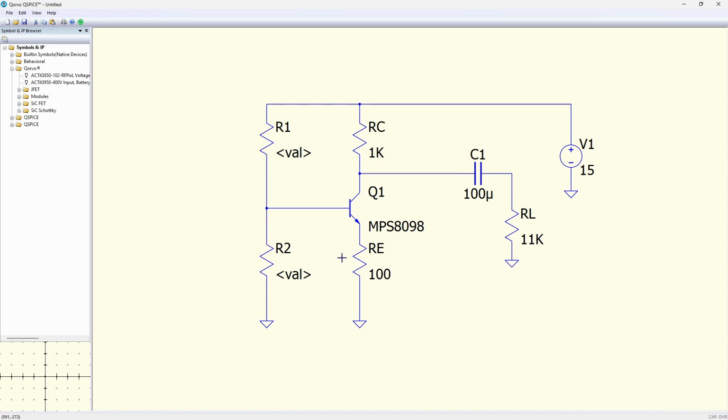But if we have 100 ohms here, now we have a significant portion of our voltage that's going to drop down here, but not that much. In this case, it's going to be about 1/10. I chose this to be 1/10 the size, specifically so that I would be getting about 1/10 of the voltage here. So we're saying maybe a volt across that resistor, and that really shouldn't give us any problems with range.